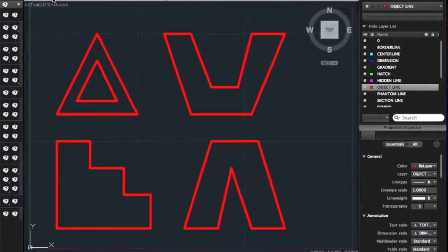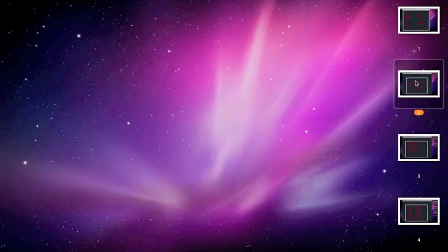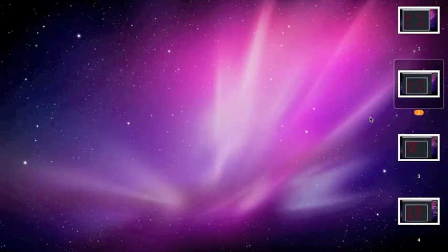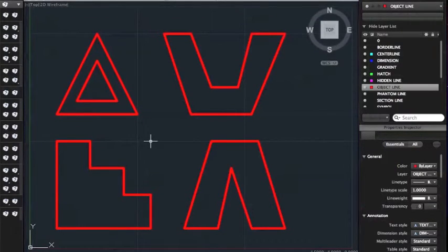So bam, we're going to go on to the second exercise, which is simply just to erase this line, that line, this line, part of this line. So we'll end up redrawing this line here. Got a couple of lines missing from here and here. So we'll do that. Bring this object back up. And the key command for erasing an object is E. So E, enter.